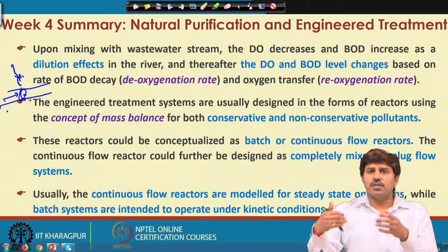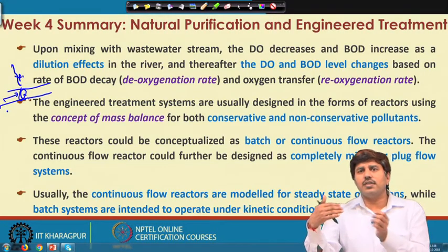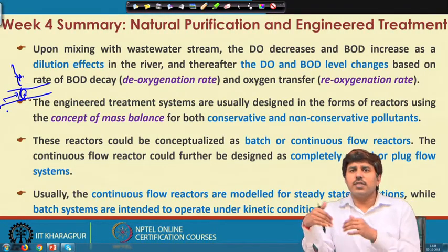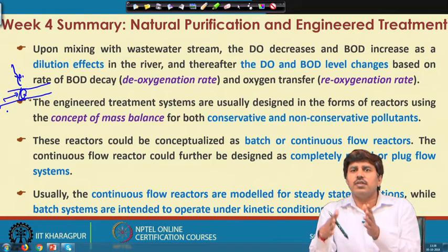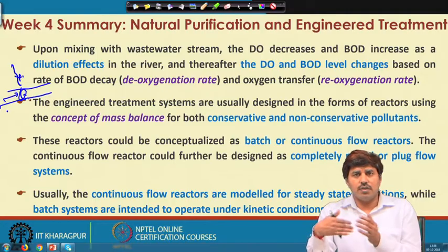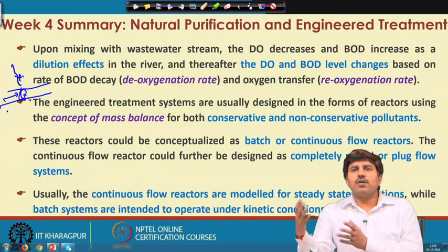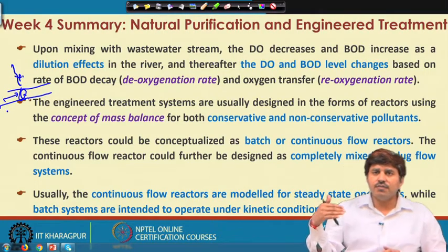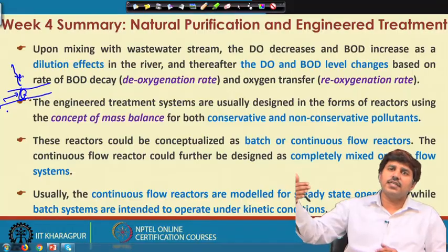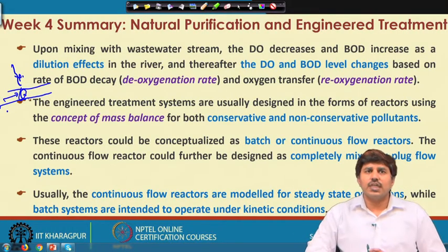So, initially dissolved oxygen will decrease. We go from the clean zone, the water goes to the decomposition zone, then the oxygen levels will reach a minimum. The river will reach the septic zone, where not much dissolved oxygen is present. Then from that point forwards it slowly and steadily recovers and moves back to the clean zone. So, we discussed all those aspects.